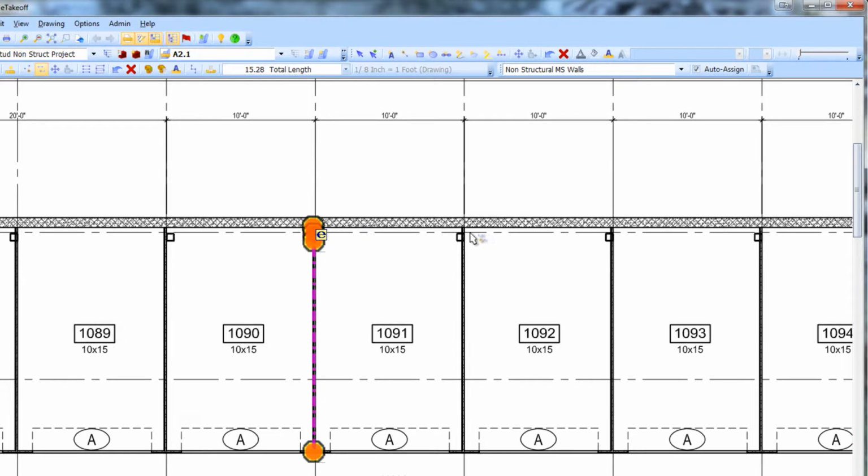You can add another wall to this particular takeoff by entering the G key, as in golf, or enter the S key to stop the takeoff. By entering the N key, again, you start another takeoff with the same defaults.